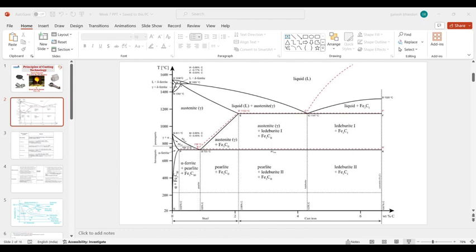Okay, so in case of annealing, you are going for very high ductility, but the strength of the sample will become very less. Okay, you can't talk about toughness. You are going to get a hardness of HRC of around 5 to 10 only, but in case of normalizing, you can get a hardness of HRC of around 25 to 30 also.